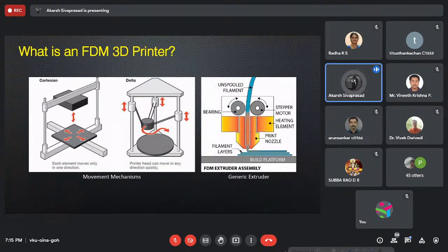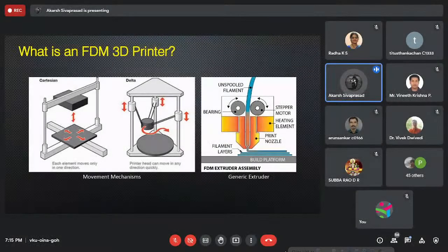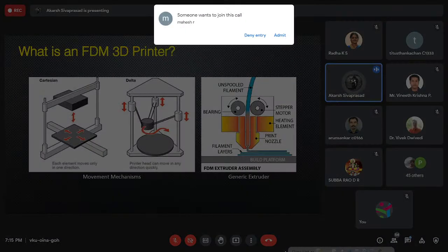As you melt your plastic, you force it through a nozzle which is 99% smaller than the diameter of the filament. You have a 1.75 filament and you force it through a 400 micron nozzle. So you have an extremely continuous, precise bead of plastic. It's a really key component of an FDM printer.